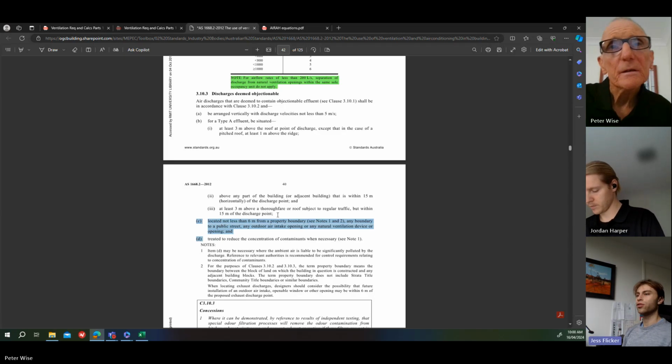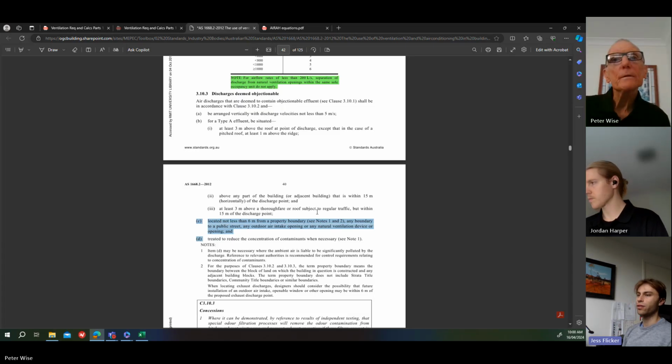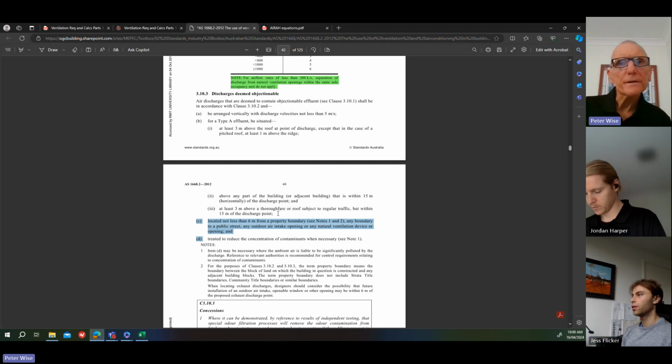I thought maybe it's like the source of the fume cupboard or something. Could you run one of these flues like 20 metres up a building? Is there any limit to how long you can run that to the roof? No. That comes back to your calculations of fan static pressure. You can have a building that's 20 stories high and run the exhaust from the ground floor. You just have to size the fan to be able to operate against that resistance.